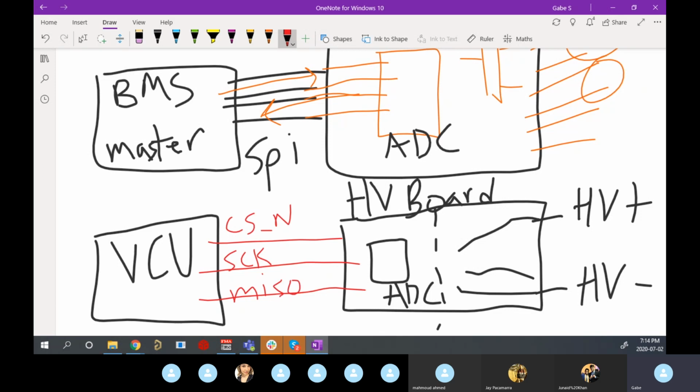So this one's a little special. All it does is as soon as you engage chip select, it just spits data out on MISO. It doesn't actually want any commands, so it's very basic as an ADC. You can't ask it for anything. You can't set values to configure it or program it. It just spits out data and that's it.